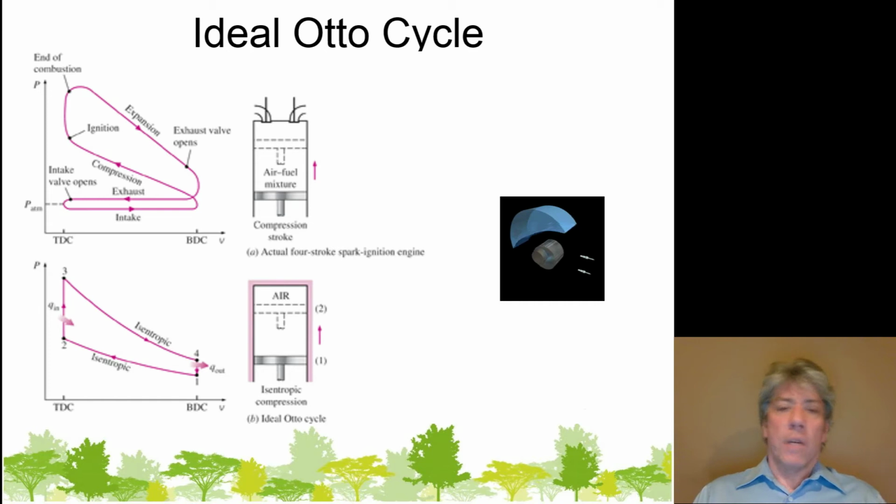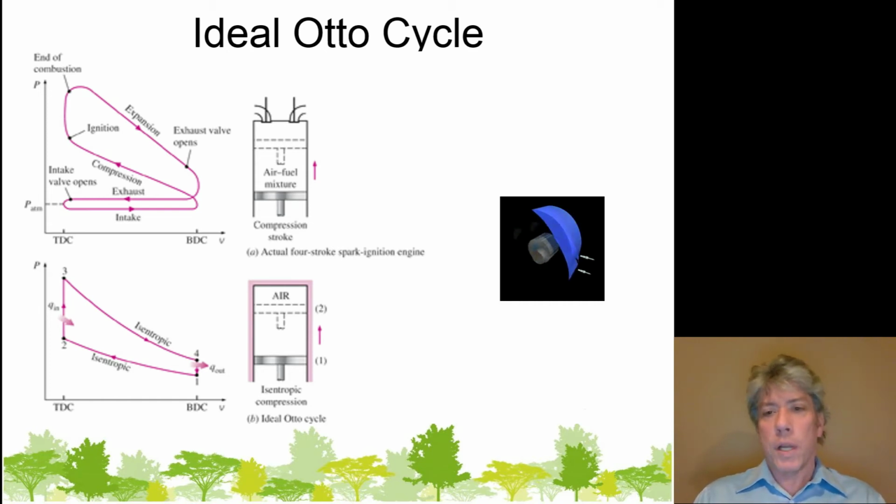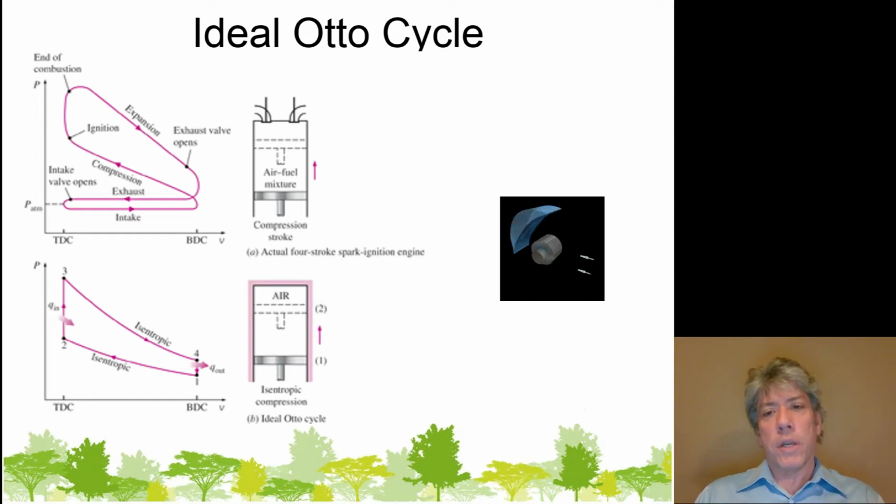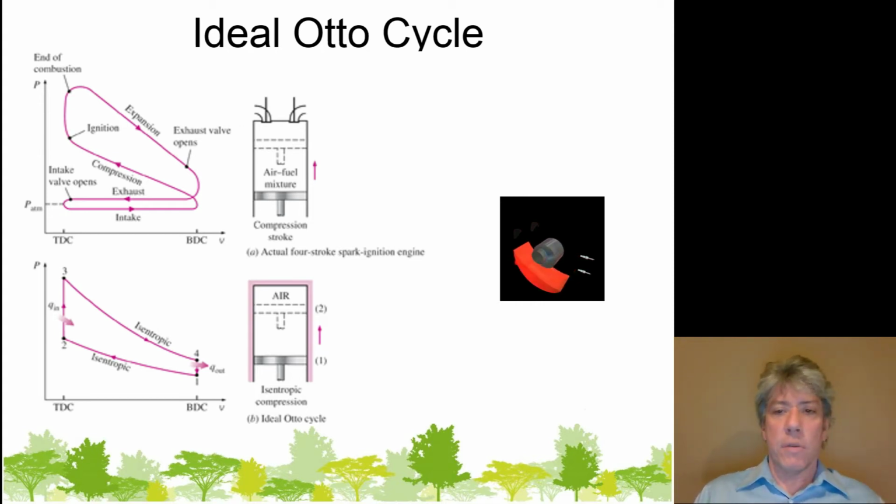So finally we can talk about the Otto cycle. Now I hope that this shows up well. I've got an animation on the right hand side, and at first it might look a little strange to you, but if you've ever seen a particular type of engine you might recognize it. In fact, what's happening is the working fluid is being shown. Here some fresh air is being pulled in, fuel is added to that air, the spark plugs ignite that compressed air, because notice the volume has decreased. The compressed hot air now expands doing work and then leaves through an exhaust port.